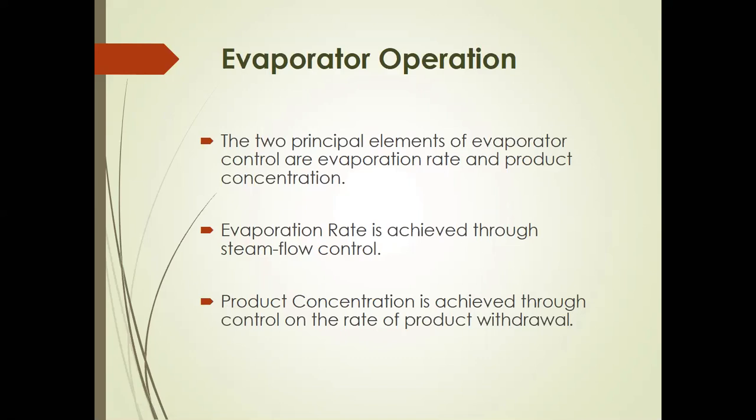In some cases, as I have mentioned in the other types of evaporator in the previous discussion, there is a settling zone inside the column wherein a portion of the thickened liquor is kept in the form of a pool of liquid. It's a pool of liquid inside the evaporator wherein part of the concentrated product is kept.